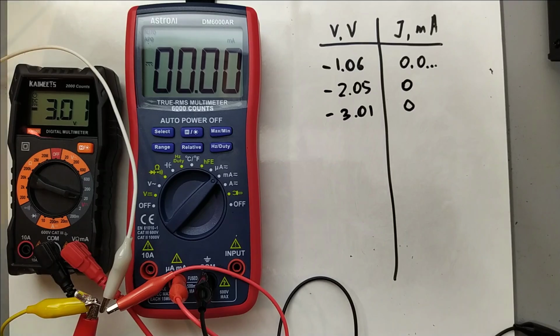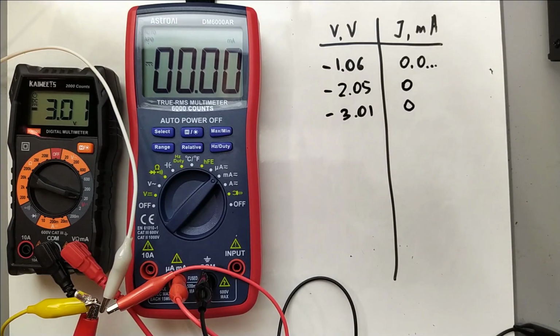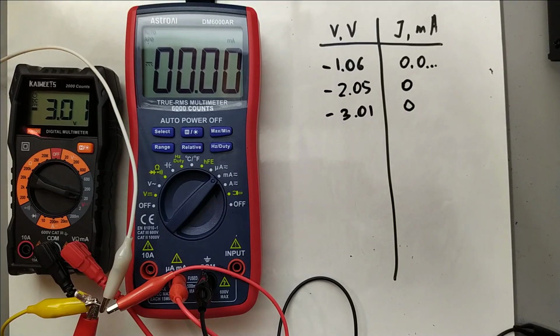Looks like either something is wrong with our electric circuit, or this device, the light emitting diode, doesn't allow current to flow at reverse bias. Most likely everything is okay with our electric circuit because we double checked that in forward bias the device was working.